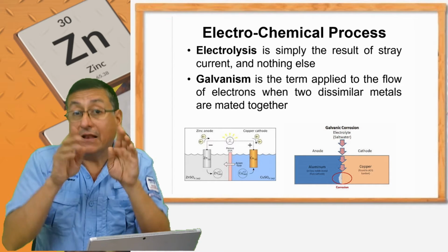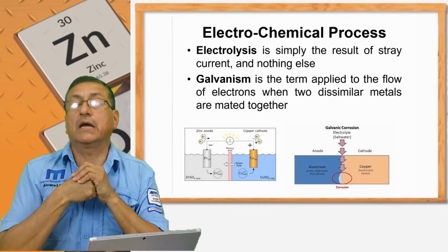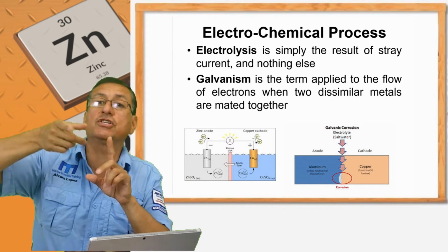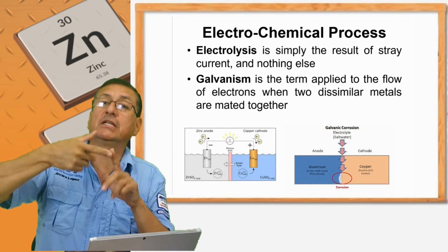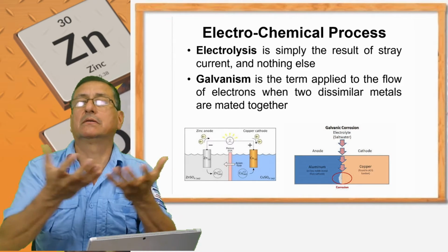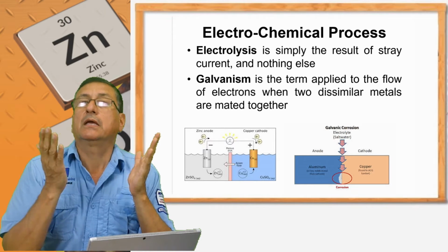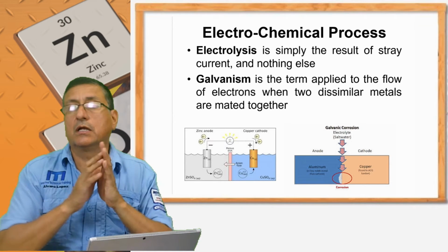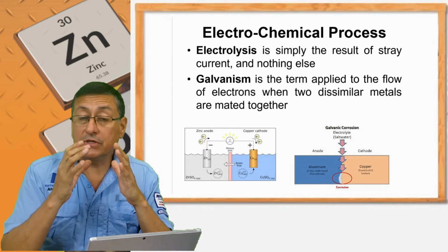Electrolysis is galvanic corrosion plus extra current in between both of them. When you have a positive cable in the harness of the engine touching the metal, that positive cable accelerates the corrosion between the similar metals, in this particular case in the block of the engine. In other words, electrolysis is galvanic corrosion plus current, normally a small DC current. For that reason, check the leaks.